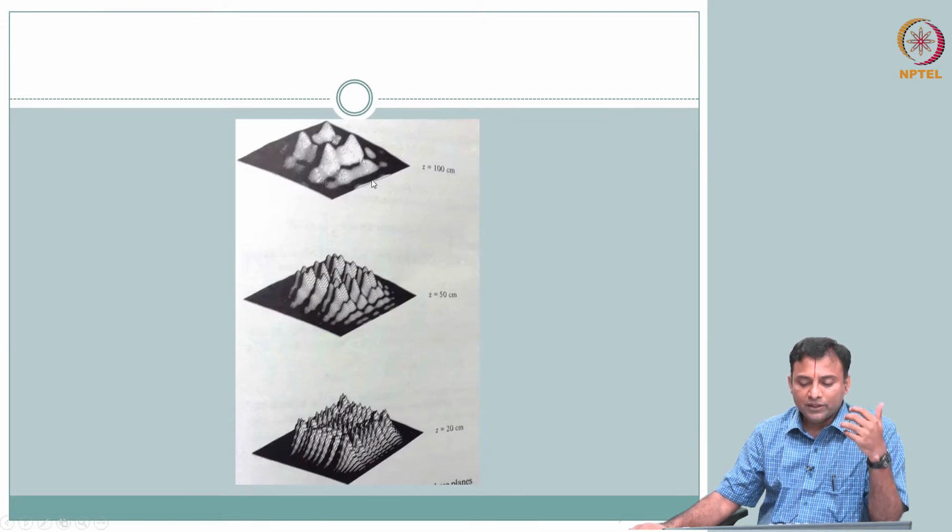So, what we will do is quickly show some. This is from a rectangular transducer. What I showed before is circular, this is rectangular, and you see a similar trend in the near field. What is a near field or far field? Remember, go back, we just made some formulations, right? If it's a circular disc, d square by 4 lambda, so 2 times that, so d square by 2 lambda.